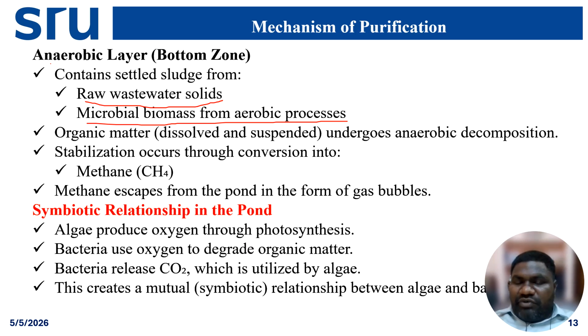So what will happen if it undergoes anaerobic conditions? The first product formed will be methane, whereas in aerobic conditions it forms carbon dioxide and water. Then methane escapes from the pond in the form of gas bubbles.